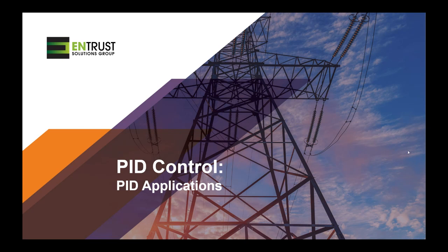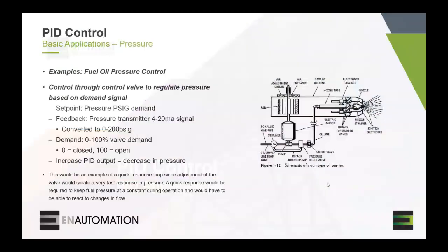But what I've seen, usually you can simulate some upsets before actually putting the system in service and get a baseline of what you think the tuning parameters should look like based on your simulated upsets, and that'll get you close to where it wouldn't be unstable when you first put this new system in. And a lot of times when you're tuning, it's already an existing system and someone wants to make it better than what they have right now. So in that case, you really need to do it online and see real-time results. So with that, we'll continue on with the presentation.